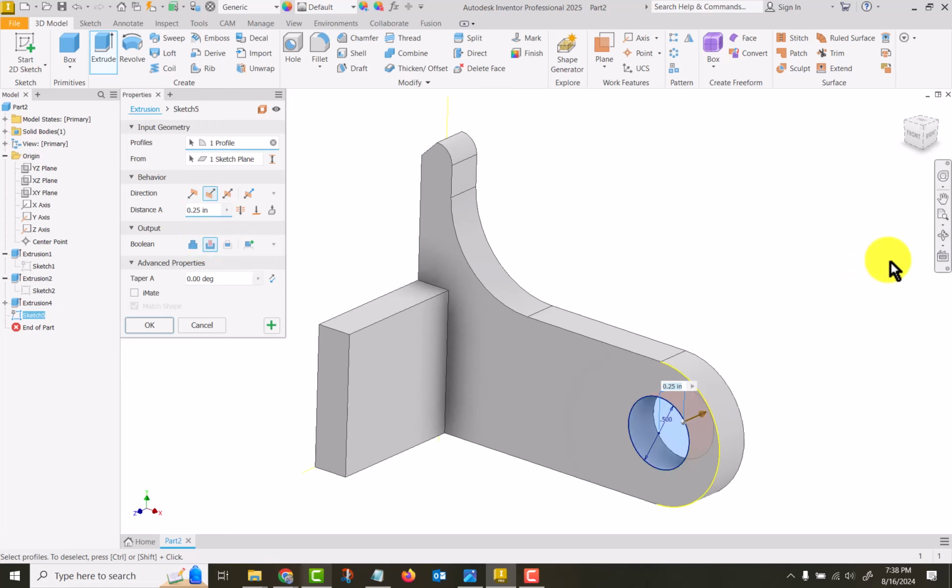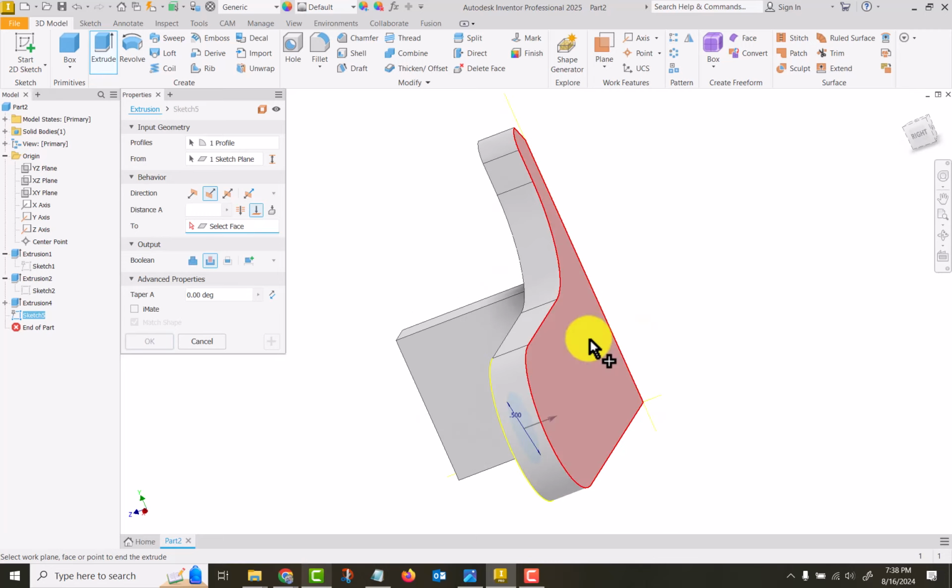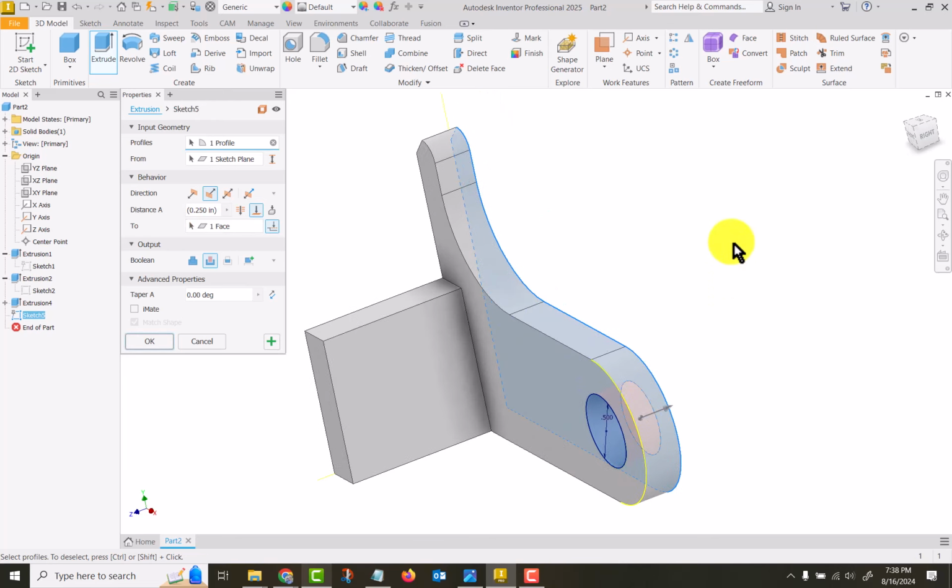and then it tells me how far it's going to cut. Now, with cuts in particular, you've got some other options here. I mean, they're there on extrusions also. You can go through all, and it doesn't require a distance. Okay, it just goes through that whole surface. If I give it a distance, or I say 2, it's going to ask me to what face I want to cut it through to. And this is rather simple, so we'll select that one.